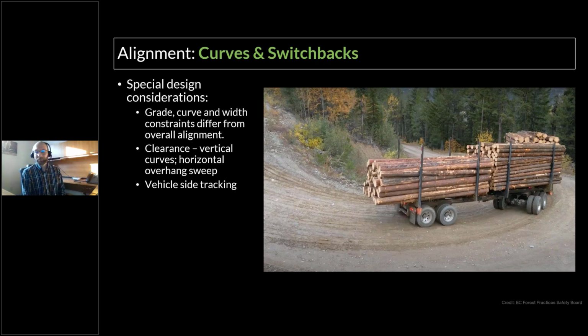There are specific software packages developed just for this analysis. In ours, we won't do that full analysis in-house, but you can develop a table for automatically widening either the inside or the outside of your curves, depending on the radius and the change angle that you're working with.